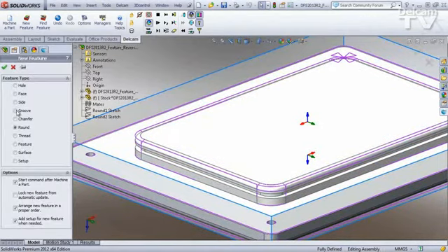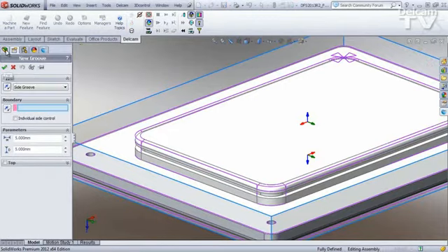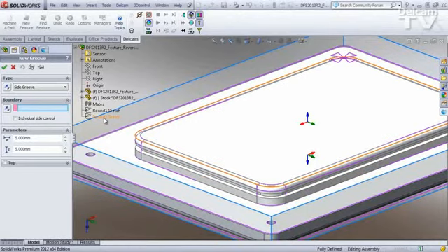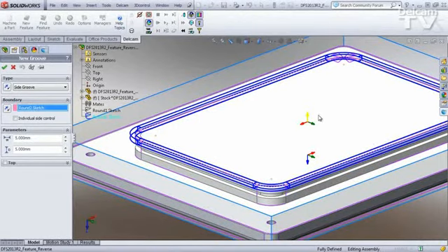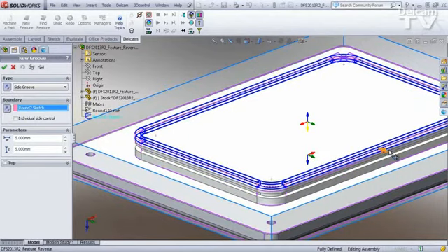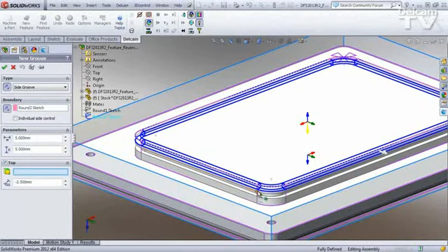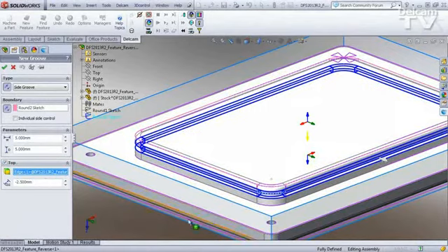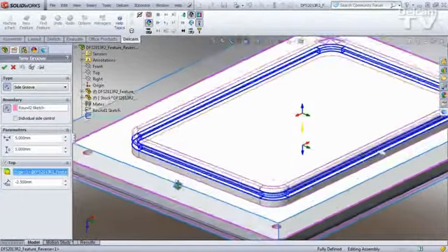New feature, groove. When you use that same sketch, we already know that the sketch normals are backward for us. We see the yellow arrow. We'll just flip the feature direction, just like that. Looks like we need to flip the cutting side as well. 5 by 5 is correct. Let's put the top of that groove down here on this edge. Of course, that puts it at the center of the groove, but I have a minus 2.5 millimeter offset to get that groove located properly.